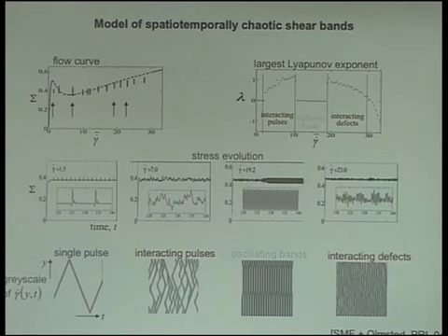So now let's look here. This is the constitutive curve drawn again. And then once we've allowed shear bands to form, we see something that looks like a plateau, but in fact at any value of the applied shear rate, the shear stress isn't a constant in time, but it fluctuates by an extent shown by the size of the blue bars here. And I'm going to pick apart in some detail 4 of these different shear rates.